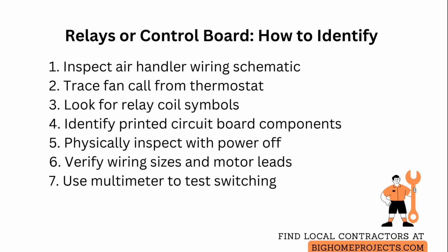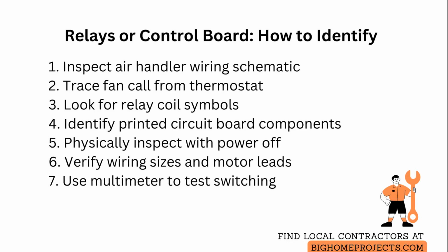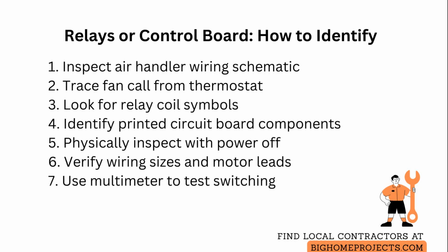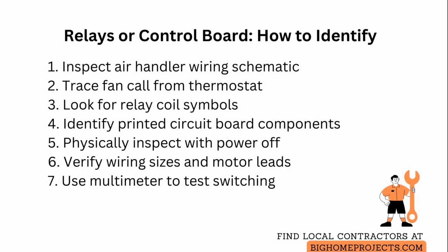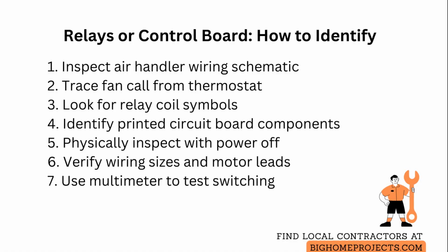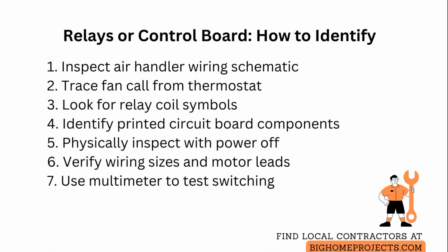And if you measure a switching element on the high voltage side only after the coil is energized, you have relays. If the high voltage is switched directly on the board without an intermediate coil visible in the low voltage circuit, then the board is switching the motor. Keep safety first by killing power and verifying zero voltage before touching terminals.